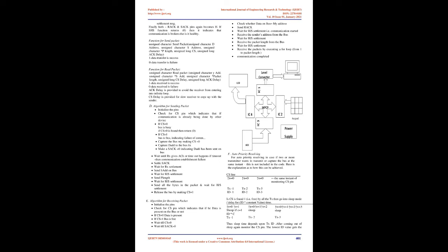In all, this function waits for the receiver's ACK until its RAC value becomes unequal to its past value within the specified time. If time elapses before that, the function returns 0, indicating unable to get a response from the receiver MC. Otherwise, on successful ACK, it returns 1, indicating ACK from the Rx was found.